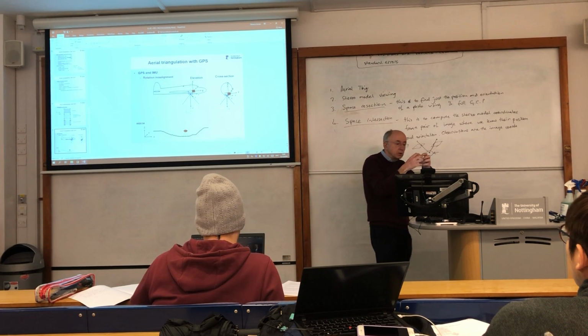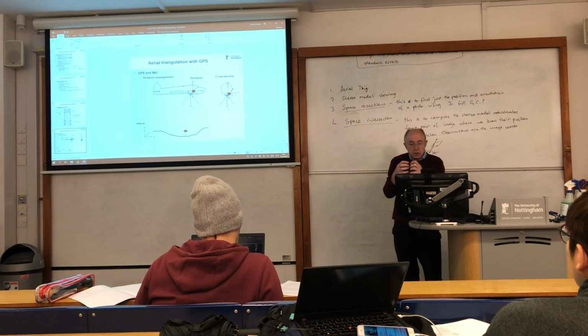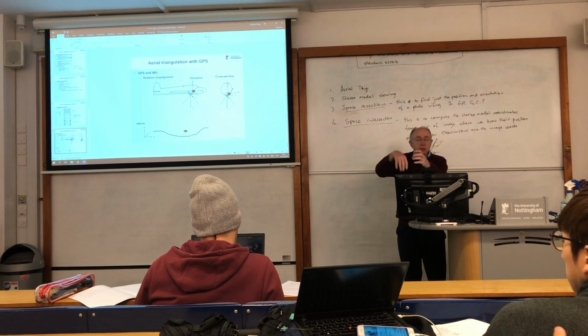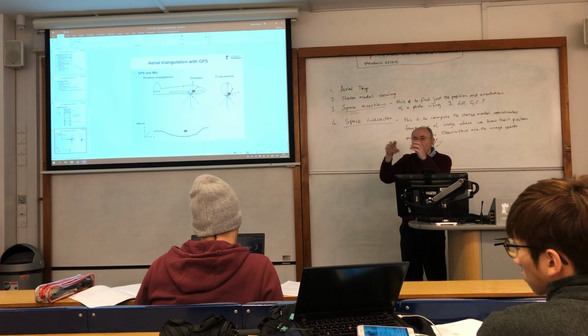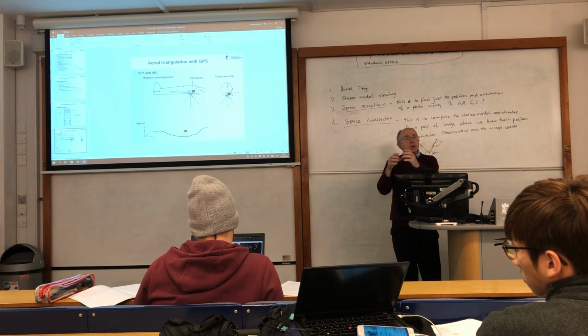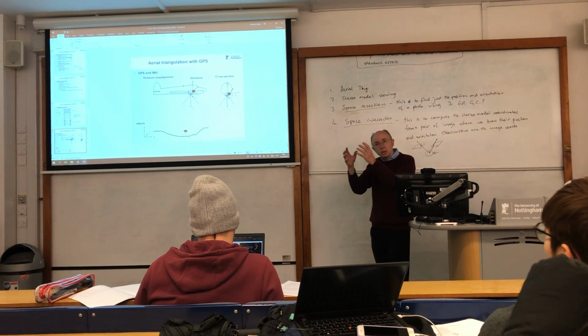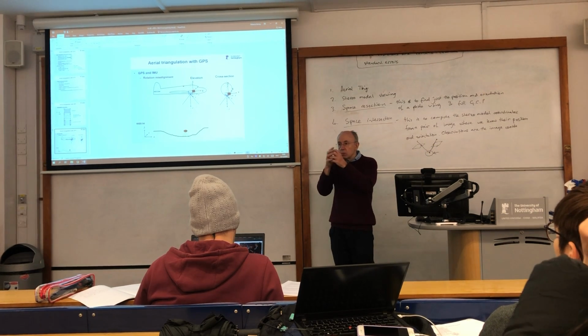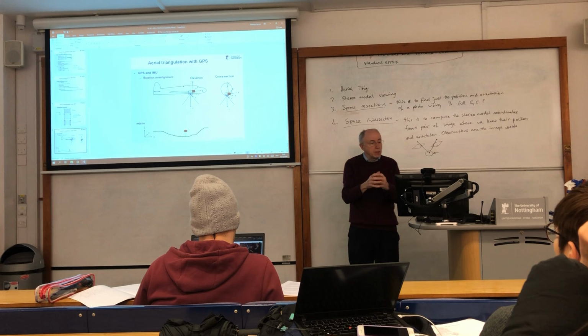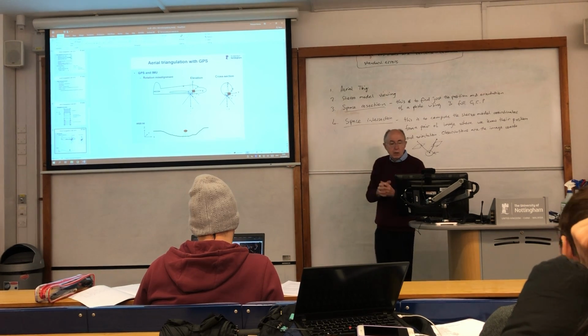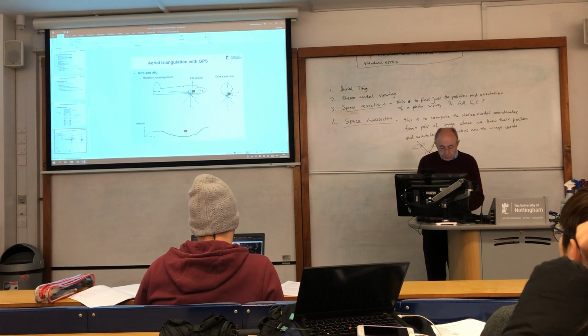The gyros and the accelerometers for the inertial measurement unit are inside the box, and the outside of the box is not accurately made enough in relation to them to be able to bolt it directly to the camera and say they are aligned. So we measure them in situ.